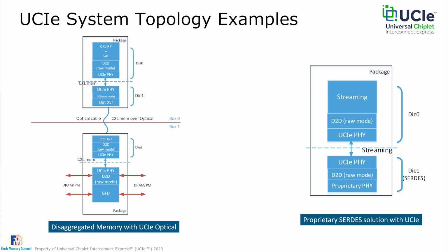Okay, and then the left one is the example of optical link, which I already described, right? And Devendra talked about that. The reason people are moving to optical is that when you get to these 200 gig and extremely high bandwidth, high bandwidth at low power is going to be critical, right? So power is becoming a big issue. So once we move to optical, what is the protocol we want to use? Now it can be any protocol.